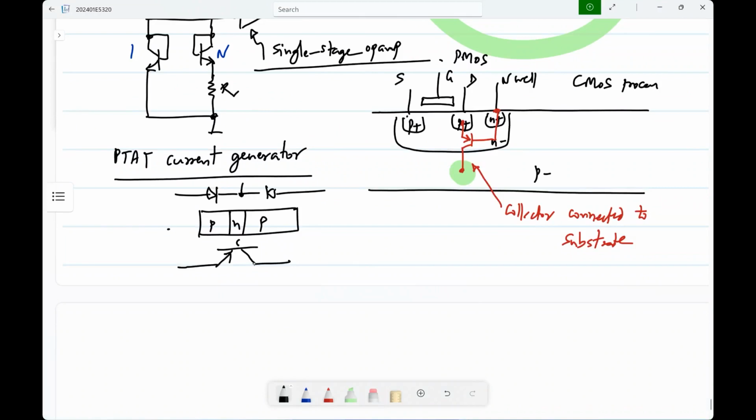I don't think any of that matters. So basically, if you make it like this, then this will be like that. It is this very thin base. Basically, most of the carriers shot from the emitter go to the collector. The thinner it is, the more of that happens. But if it becomes very wide, then all of this current will go there. It's like having two separate diodes.